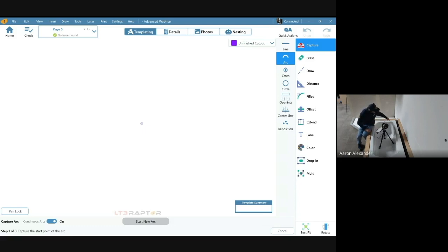So I'm going to start at this tangent point back here. I'm going to start right on my little pen mark right there. And now we got to worry about draft. The height that you're aiming your laser at, you want to keep it consistent going around this thing, because obviously there's more draft where the person lays in the tub than where your feet are at, right? So we definitely got to pay attention to height on this, especially where there's a lot of draft.